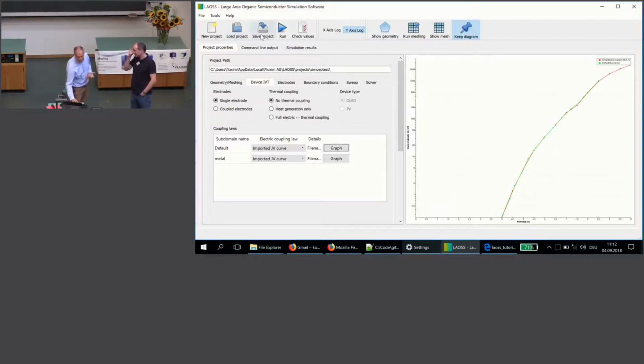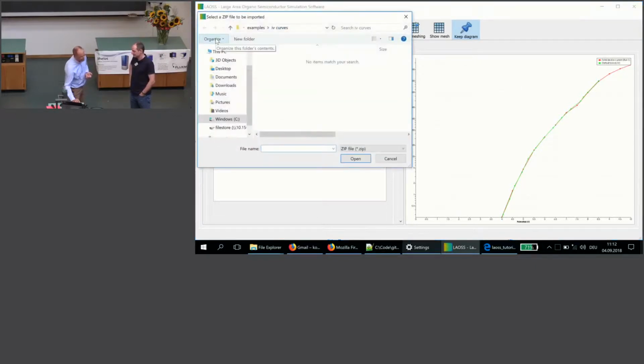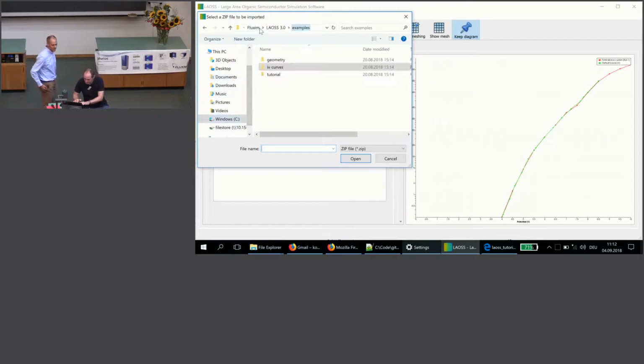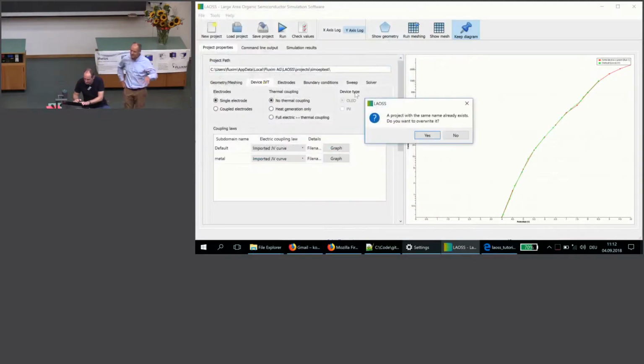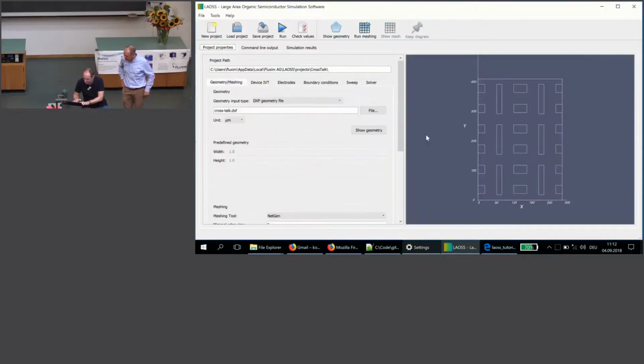Maybe now that we have an example of OLED and electrical modeling, let us open the pixel crosstalk. Pixel crosstalk is an example where physically it is very similar to what we have shown here for the simple OLED, but in a pixel array, we have a few more domains. So for each R, G, and B pixel, we need to select the JV law.